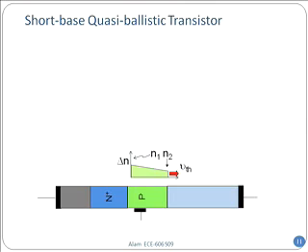You see, if you make the base very small, so it started with, let's say, several hundreds of microns in the beginning, gradually you're making the base smaller and smaller. Why do you make it smaller? Because remember, the base width is in the denominator, because the shorter the base width, the more the gradient, the faster is the current, and therefore more gain. Now if you keep making it smaller and smaller, the diffusion velocity, which is D over W_B, will keep increasing, right? Because the gradient is more, it will go away faster.